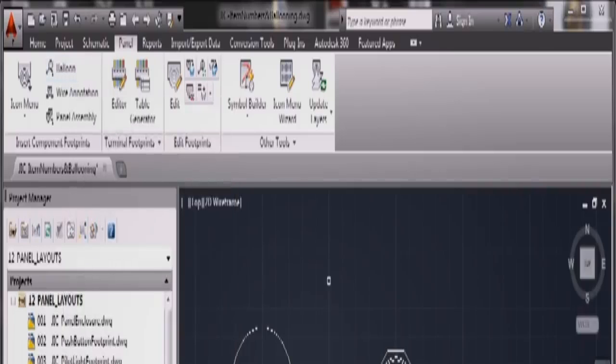I'm going to click on balloon and come into the drawing area, and you can see there, it says on the command line, set up or select component for balloon. I'm just going to change my drafting settings. I've got that jerky snap and grid going on. Let's just lose those. I'm also going to switch on dynamic input so that we can see that on the pick box prompt there. So it says set up or select component for balloon.